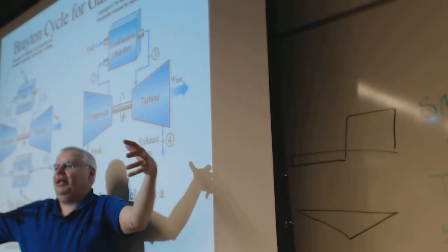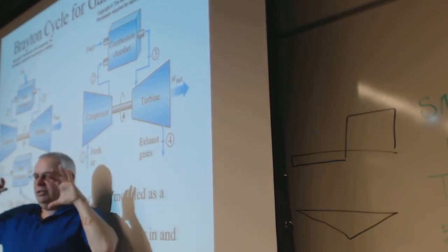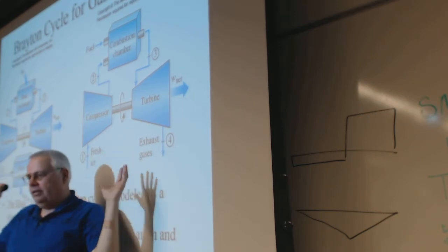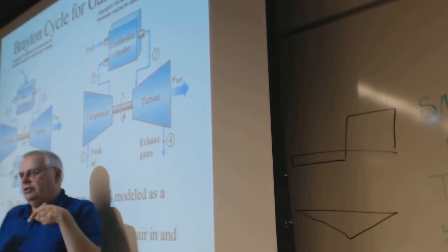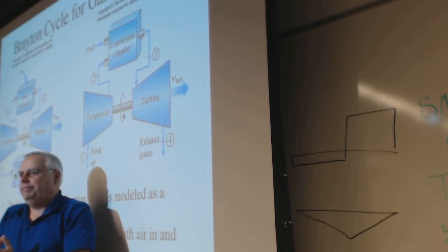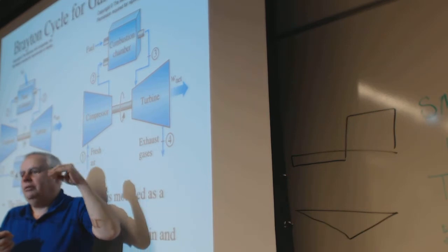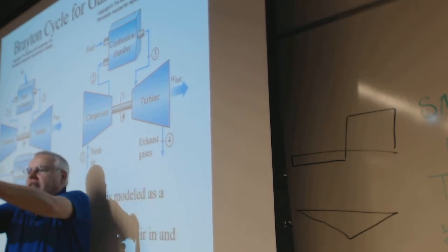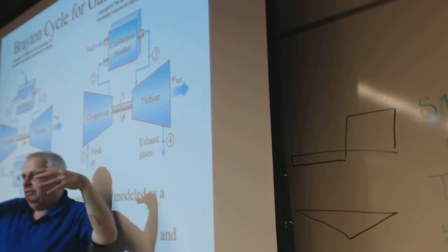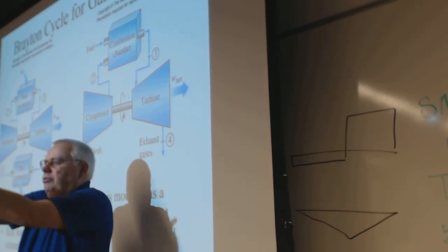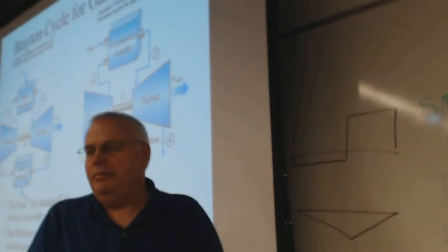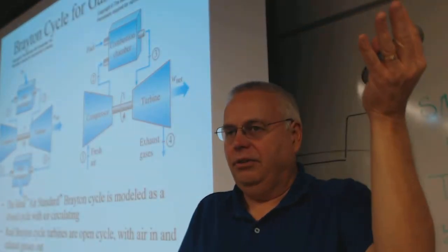It increases the mass flow rate around the engine, which then blends it back in with the exhaust, which was going slower now, but now you've increased the mass flow. It doesn't all go through the engine. Some of it's going around, not burning air, and then the two connect together at the exhaust pipe. And the fast speed gases here blend with the mass flow rate coming through, and everything comes out. The energy gets blended back together, but now you've traded mass flow for velocity.